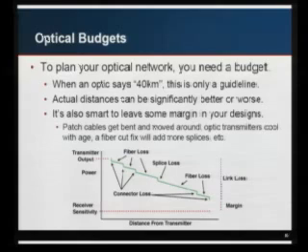You start with a specific transmitter power. You see fiber losses along the way. You see big steep fiber losses when you hit certain connectors or splices. You get down to the end of the link and you need to make sure that you have enough signal left over to stay above your receiver sensitivity, and also to have a little bit of margin built in,